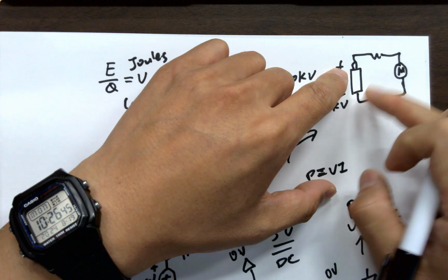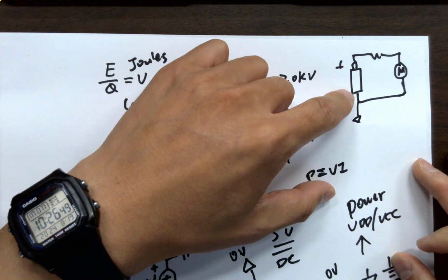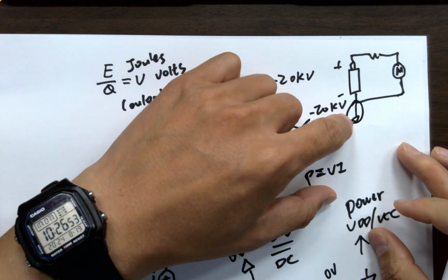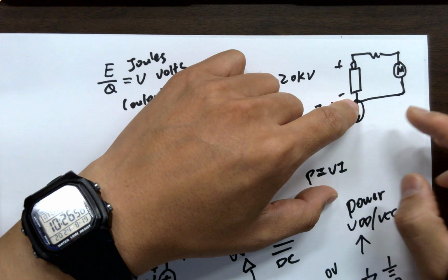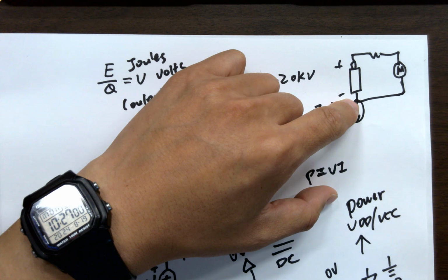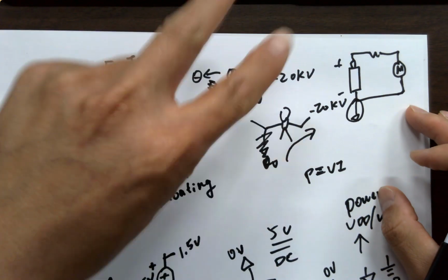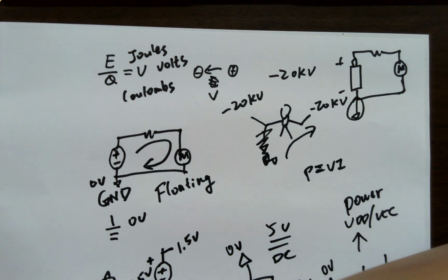But you should know that we usually ground the cathode of the power supply. We just draw it. It's not a physical thing on the board, but we treat it as 0 volts. You may still be confused about how we know it's 0 volts. It all depends on how you measure it. A multimeter usually has two probes, a black and a red probe.